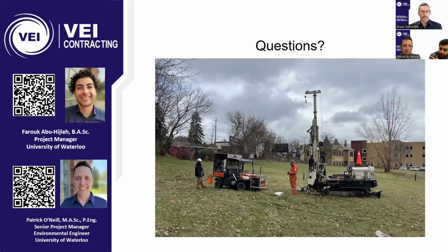It's a good question. Technically, yes, they can be completed in those really tight materials. I wouldn't do it just because it would take forever for those things to dissipate. You could be looking at hours or days, really. The operators were trained to look for those sand seams, those really highly conductive zones below the water table to conduct your dissipation tests just for an efficiency standpoint so that we can capture that data and move on. So they can be completed in those fine grain materials. I don't recommend it, and I only would recommend those coarser grain materials to be completed dissipation tests.